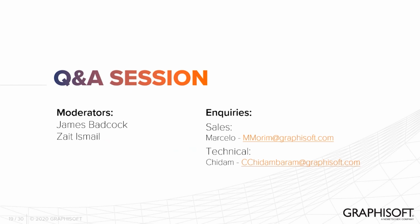Yeah, thanks, James. Hi, Freyas. Thank you very much for asking the question. Yes, you can do it. I think James already answered. Yes, you can label any element, including objects as well. So it works with actually labels, any labels. You need to set your labels first, and it can be saved as a favorite or whatever. Then once that label is active, you can actually tag any element in the same way. Thank you. Okay, thanks.